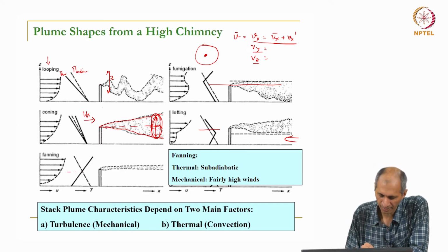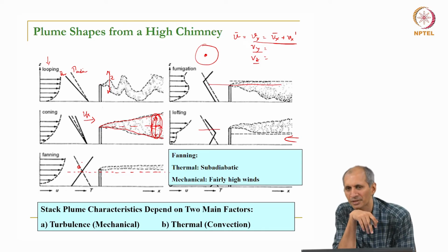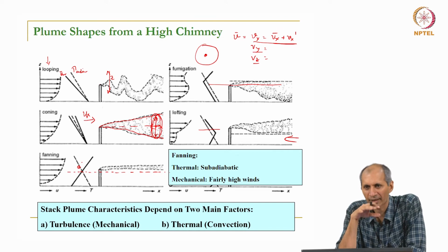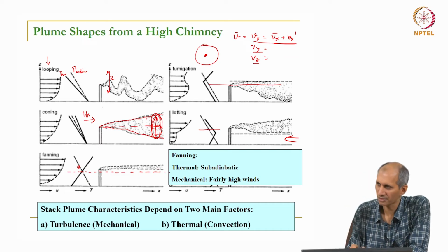So you can see that this is the mixing height, but the pollutant source is right above this mixing height, okay. So if a pollutant is released, it is following this line, but you see that in this particular instance the temperature of the plume is less than that of the environment. So it tends to sink back to its source point, or it sinks back to the mixing height. So it stays very close to the mixing height and it goes in this direction.